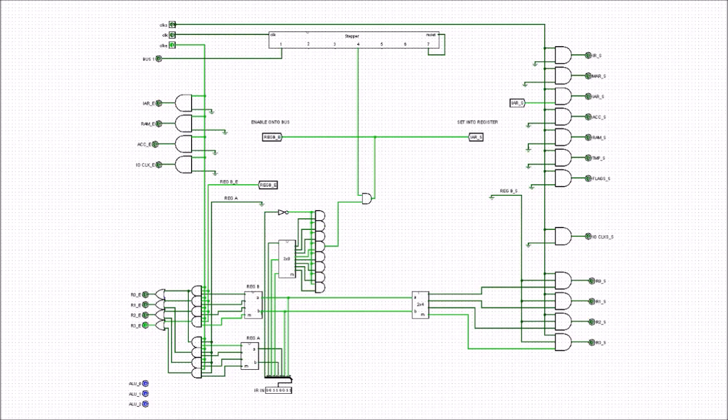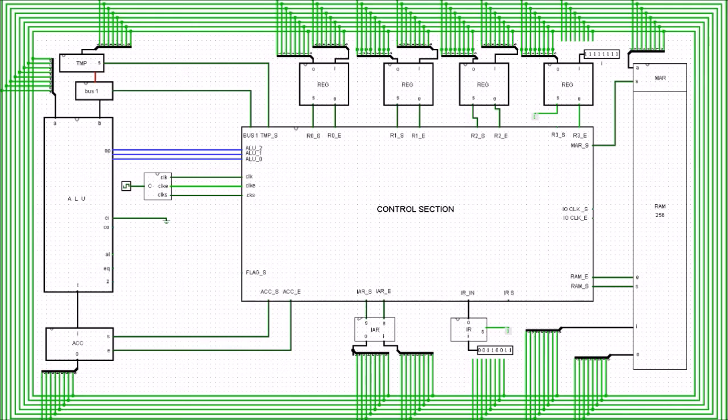So we go up to the top. There's the contents of register 3, which are all 1s. It's all going onto the bus, and we're going to set that in the instruction address register. Whenever the set goes high, that's the set going high, now that value is in the instruction address register. So it means that the next instruction that the CPU executes is going to be in byte 256 in this RAM. So that's quite straightforward.